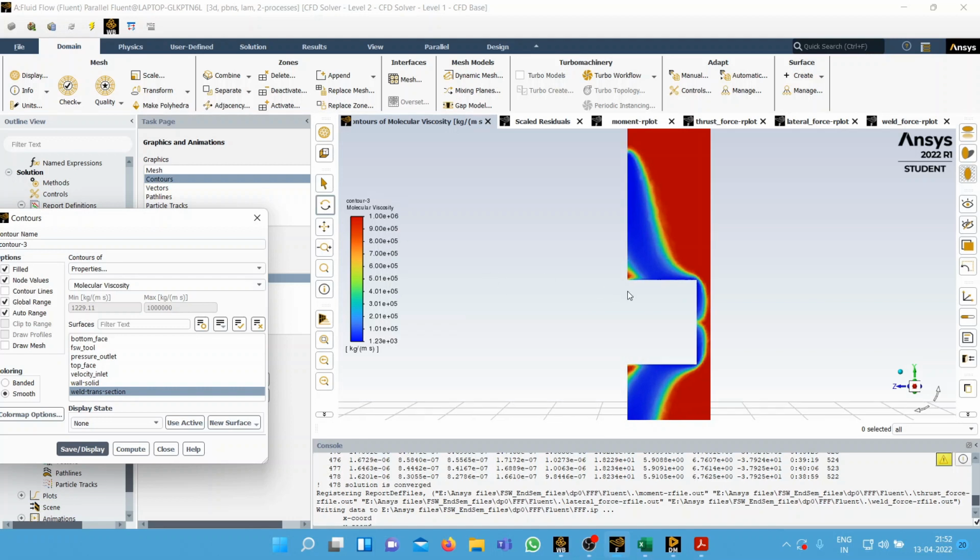Here we can see that the viscosity is lower. It is lower because this region is very hot, and due to the plastic deformation, as the tool rotates here, it stirs the workpiece, that is the material in this region, and the flow of material becomes easier, due to which the viscosity will also be very low as the material softens in this region.